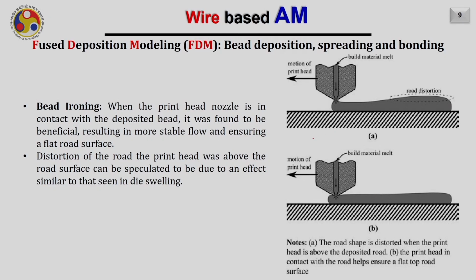To avoid that, we push that bead immediately when it comes out of the nozzle as well, in such a way that your top surface doesn't get affected much, or its shape remains constant, meaning to say the height, the distance between the top surface of the deposited bead and the bottom surface remains constant throughout. To make sure of that, we do the phenomenon like this.